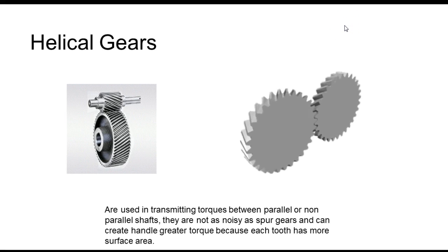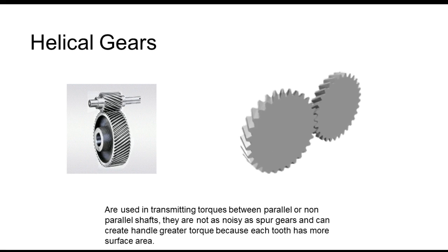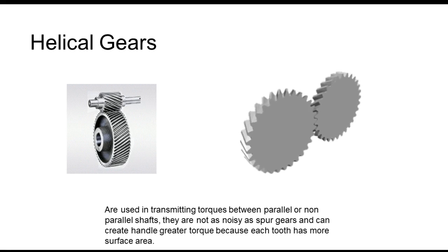So these are helical gears. So they get a different name, right? And what's the advantage of a helical gear? More contact, which means they'll handle more load. And also, what's another advantage of these? They're quieter, right? They run quieter. Yeah. So they run smoother. They run smoother at high speeds. Biggest disadvantage is they're more expensive to make, right?